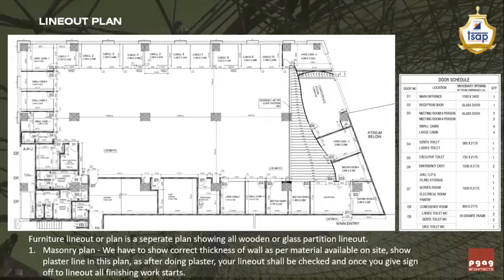Now, while giving the layout dimensions, it is very important for you to know the actual dimensions of the site. Sometimes we get the drawings from the architects who designed the building, and based on those drawings we start our work. But as per site dimensions, many things change. Because of that, it is your first responsibility to check the site dimensions and incorporate them in your drawings itself. After the concept stage, you convert your drawings into a format where it correlates with actual site dimensions.